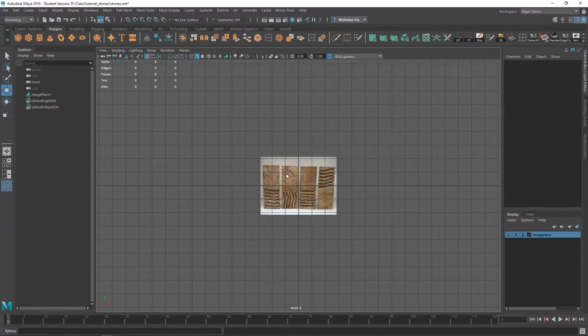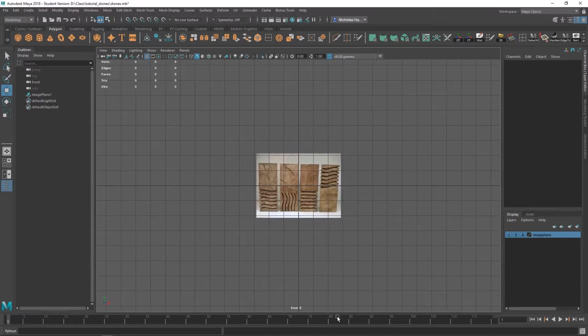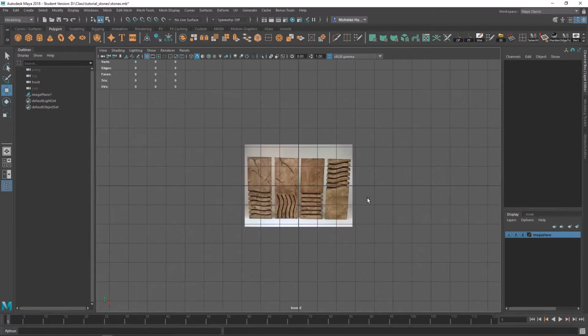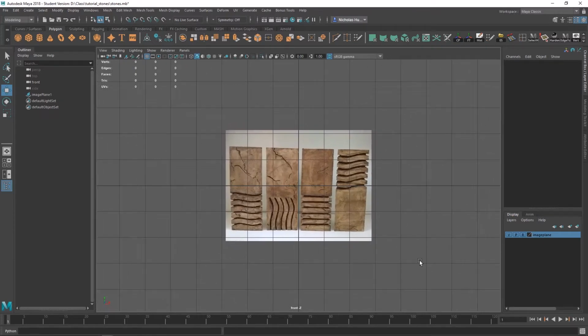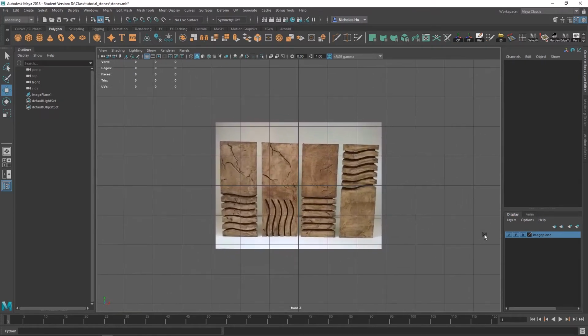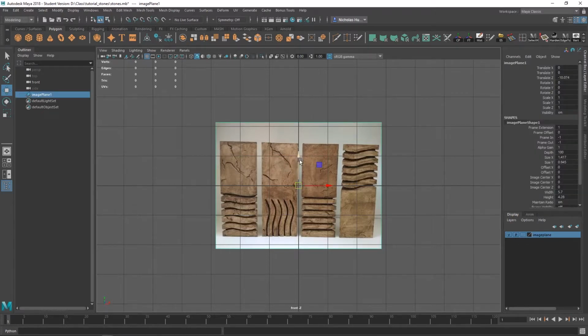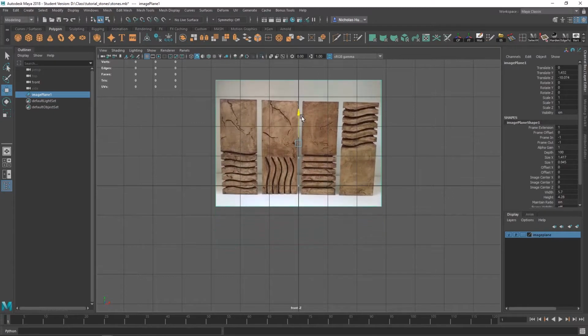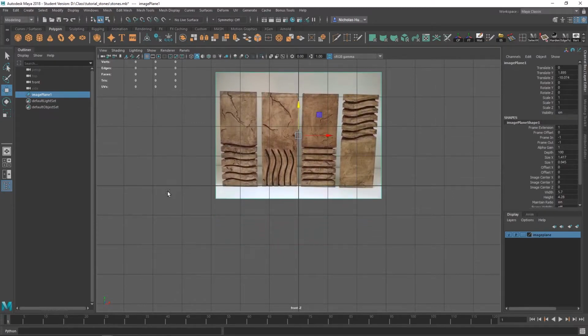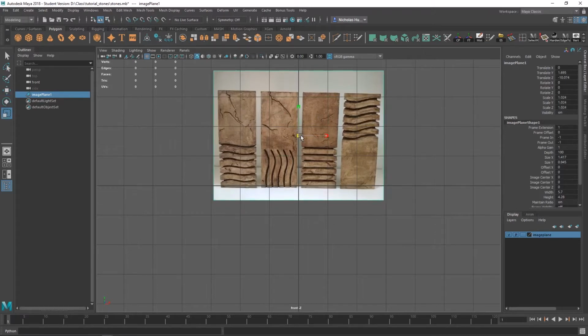You can zoom in by holding down Alt and right mouse button at the same time, then pull the mouse towards you. You should zoom in. Technically it's not a zoom, it's a dolly, but still, it'll get bigger. Let's click that R one more time to unlock it, then click your image, and then with W for move, move it up to where the bottom about meets your horizontal plane here. And we might even want to scale this up a little bit.